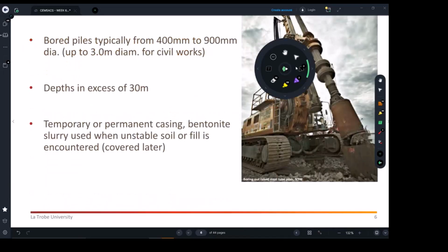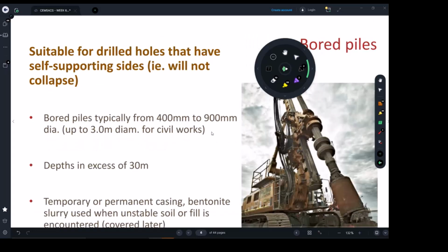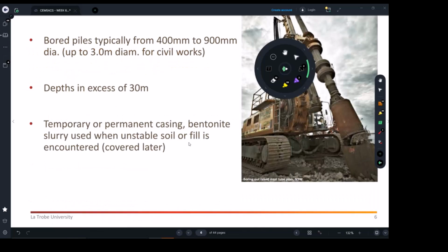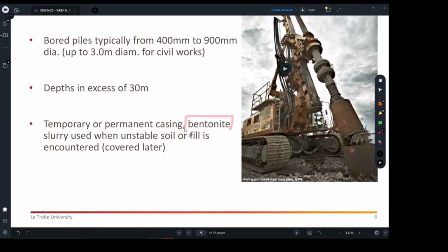Sometimes, as we're going to talk about next, this type of topic is linked with what we're talking about later on. Because if the soil starts collapsing in on itself, or we hit a water table, so we've got water leaking from the underground, then we can use the technique of placing bentonite. We will talk about bentonite. It's just another kind of product with high viscosity that will stop that water from getting into the hole that you're digging, right? But we will talk about this later.